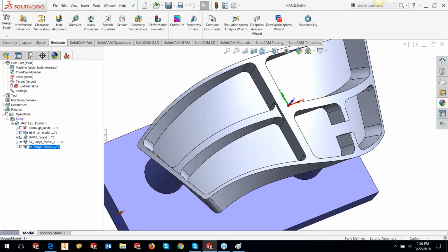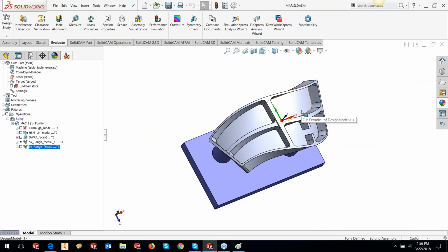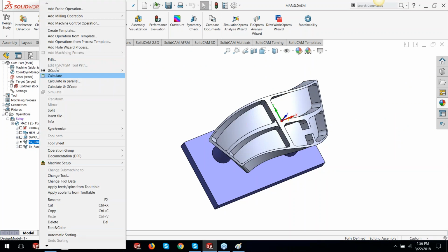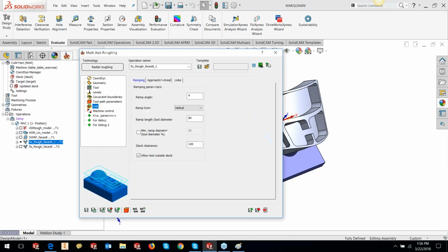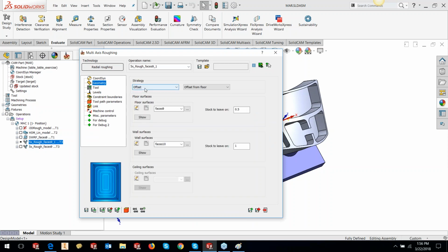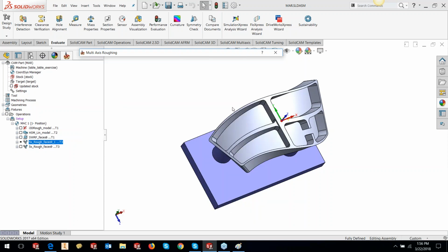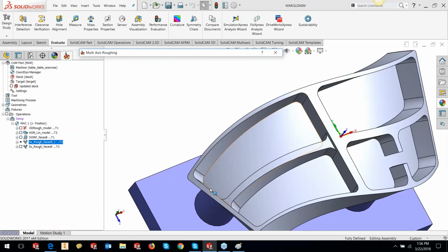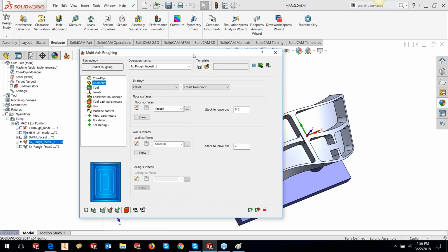Another way of cutting it, if you don't want to use iMachining and if you want to use a regular roughing kind of a method, is to use the next method, and that's the offset style. In offset style, it's basically going to generate the periphery here. It's going to find the periphery, and it will just keep collapsing the periphery by the equal to the side step till it doesn't find any more area to machine. So it's simple, like our contour roughing in 3-axis.